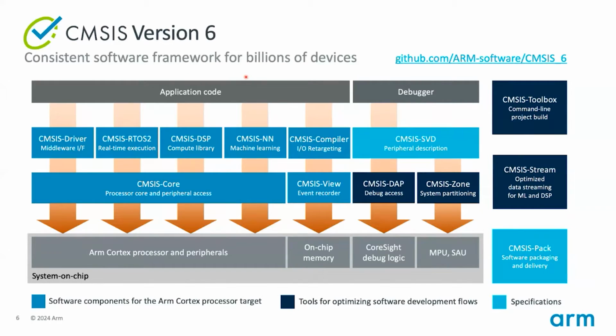We have also optimized the structure of CMSIS. So the ARM CMSIS pack today only includes the CMSIS core and the APIs that are available through CMSIS. Other components such as DSP, for example, or CMSIS NN, are now available through separate repositories for better maintenance and faster release cadences. We usually release a CMSIS update twice a year, but our colleagues who are doing the DSP, for example, are much, much faster. So that's the reason why we have taken that out.